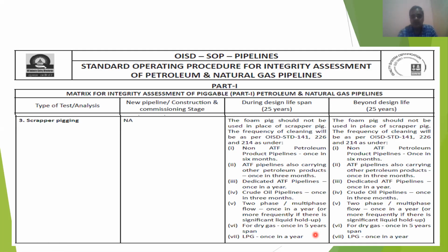So we have to carry out the scraper pigging as specified in the SOP. So beyond design life, the foam pig should not be used in place of a scraper pig. The frequency of cleaning will be as per OISD standards 141, 226 and 214 as under.